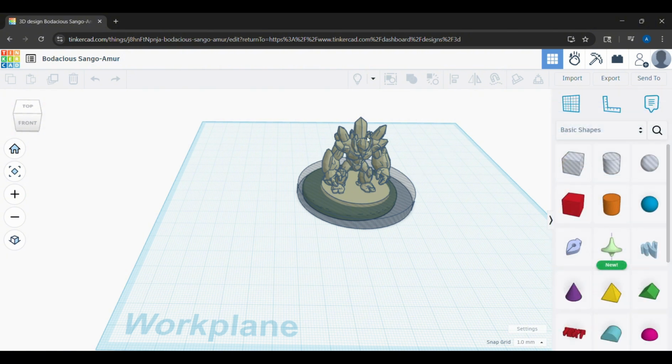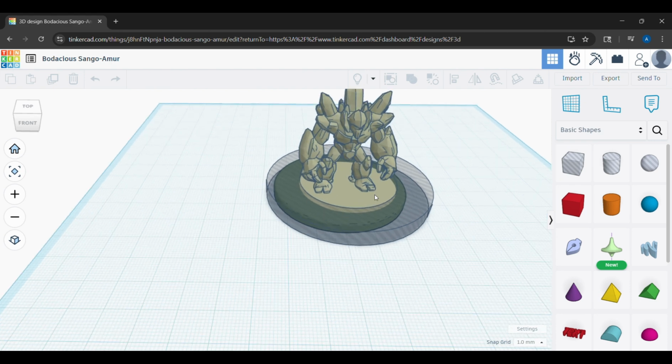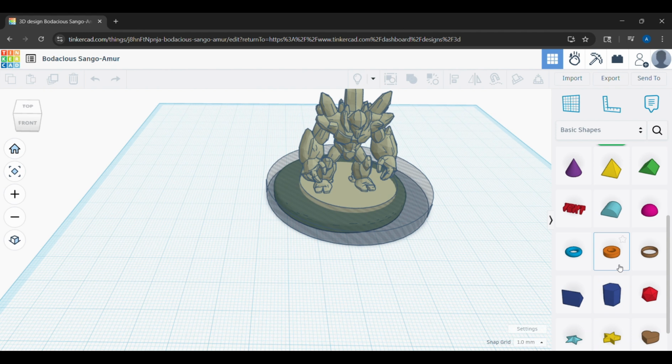Like I did not design this miniature. However, I wanted to have a smaller base, so basically I brought it into TinkerCAD. I used a pre-made ring here or a tube and basically made it as a cutting action, so it cuts away this existing material, and then I can now export this as an STL with a much smaller base. So I use it for editing.